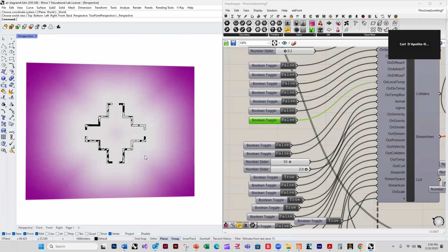Yeah, so the buoyancy and gravity operate just in the two-dimensional plane that you set it in, the way I've set it up. So if you're doing a plan, you will never turn on the buoyancy. And if you're doing it vertically, you will turn it on if you're simulating with temperature. And if you're not, you'll just leave it off.